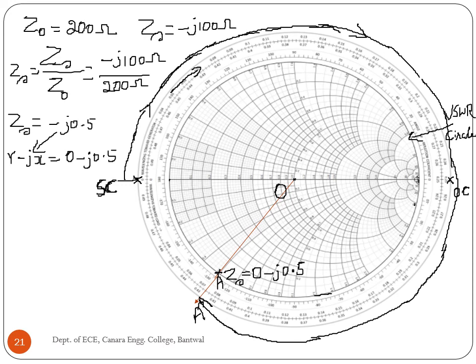When we move from SC till the A dash line, it coincides with the line at this point. The value of that point is 0.42 wavelength, which is equal to the length of the transmission line. It's the answer for the fourth problem.